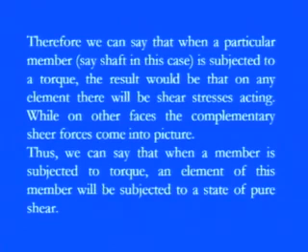But if the object is in equilibrium, we always have an equal and opposite part, and the technical term for the equal and opposite shearing stress is complementary shearing stresses, or complementary shear forces. So, for any object under rotation with a couple acting, all elements under the influence of this couple experience shear forces, and they tend to move along the circumference, not along the axis, just toward the plane part.